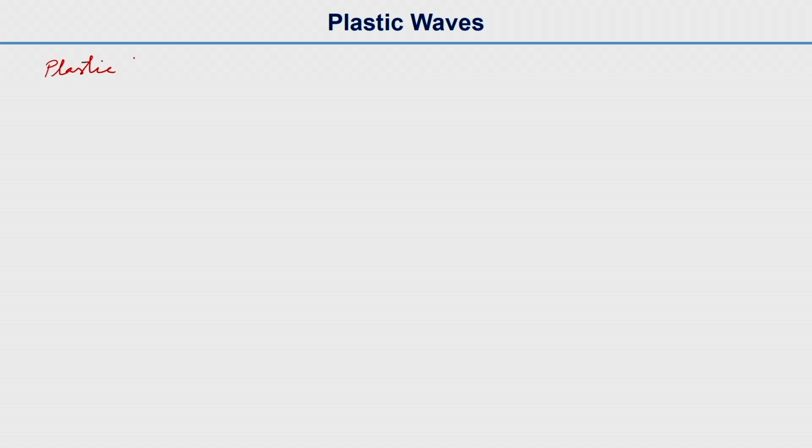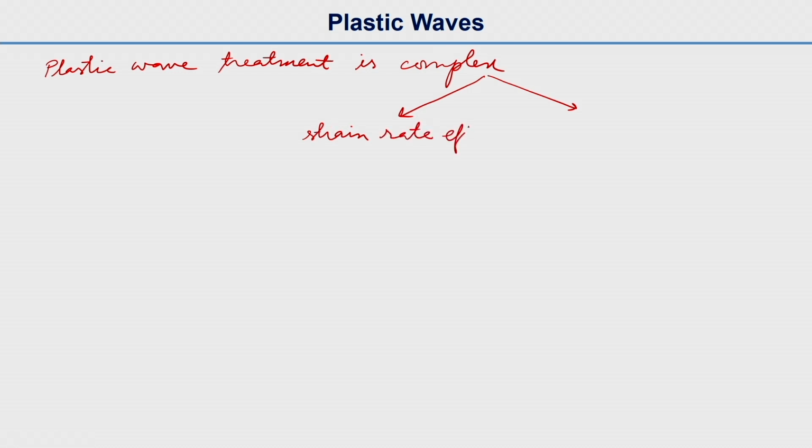So, we will discuss the plastic waves now. The treatment of plastic waves is more complex than the elastic wave due to, first, strain rate effects that we have just discussed, and second, effects of strain rate history, what we have just discussed.